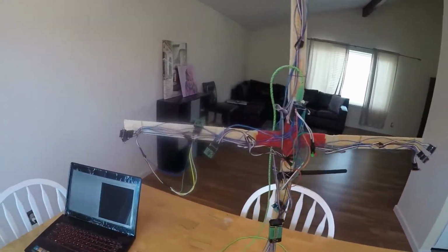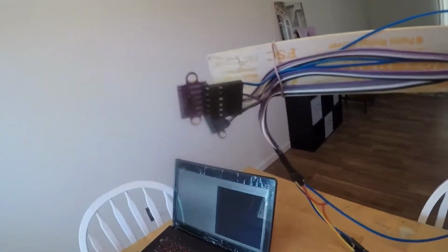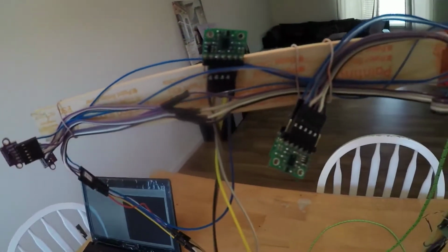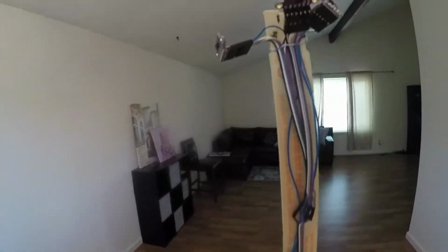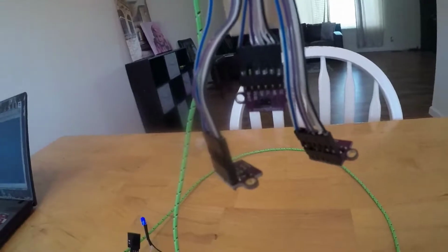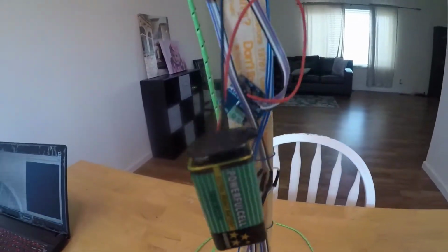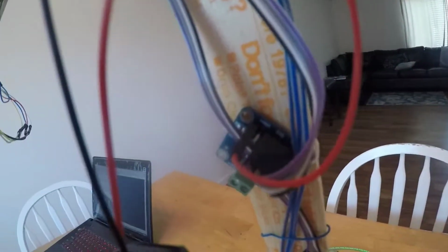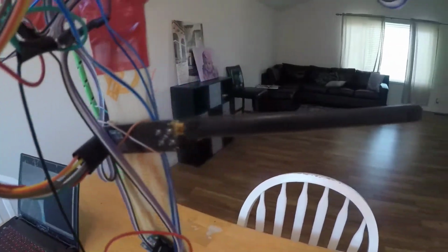Shown here is a mock-up of a quadcopter body along with the wiring harness connecting the LiDAR time-of-flight sensor array, consisting of a total of 14 time-of-flight sensors, to the Teensy microcontroller. A 9-volt battery stands in for the drone battery, which is connected to a voltage sensor. Battery voltage and proximity data from the time-of-flight sensors are sent wirelessly from the drone via an RF transceiver.